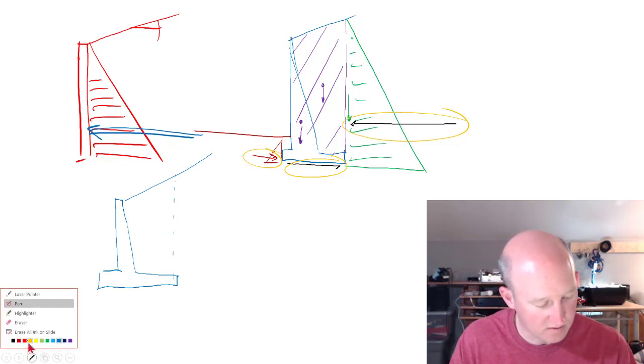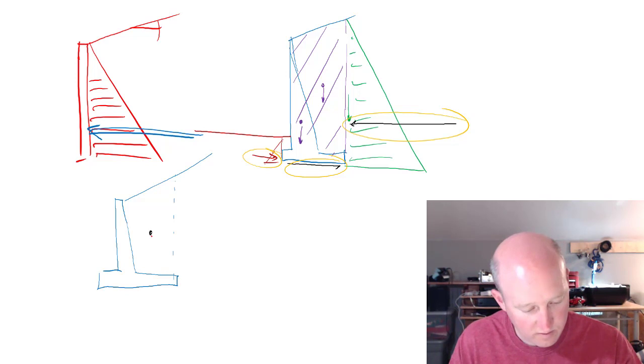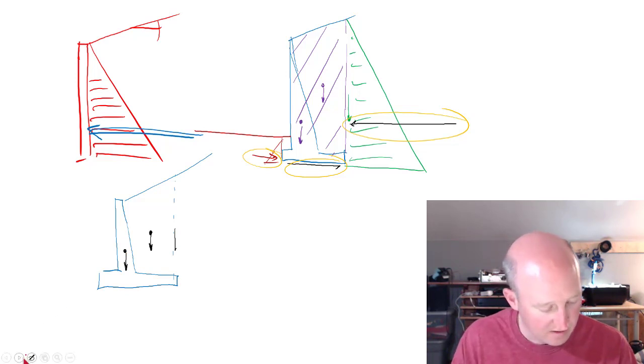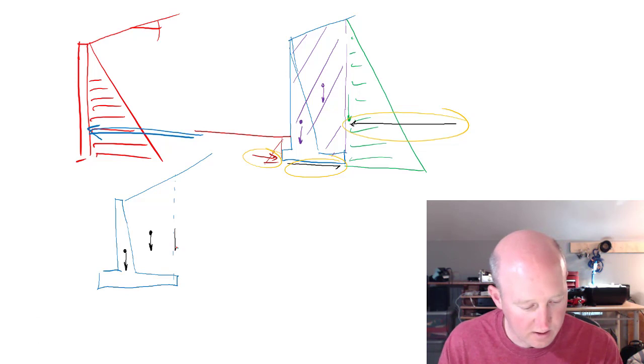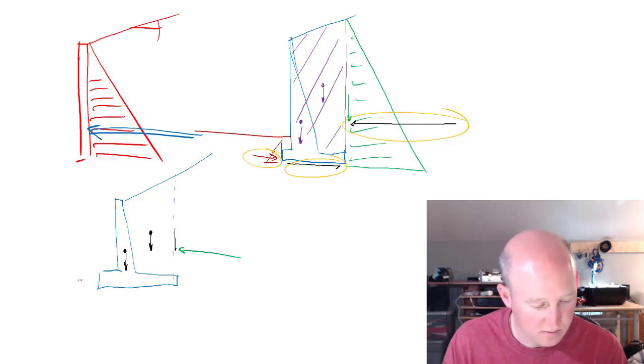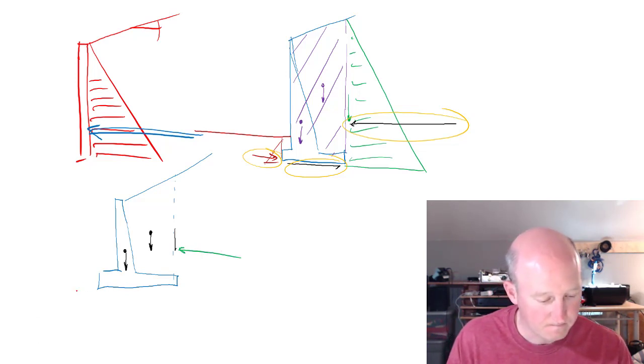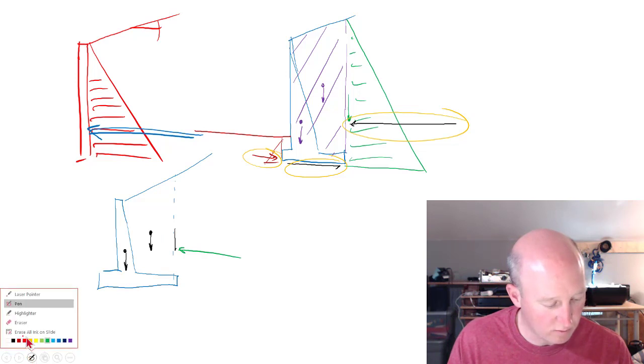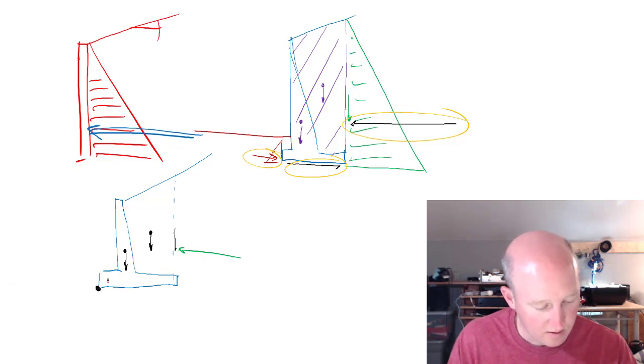with all of these same forces, so we've got a weight of soil, we've got a weight of concrete, we've got a frictional force that's acting on the back of the wall, and that's due to the soil failing. And then we've got a horizontal resultant. And what we would do is we would analyze this thing as a sum of moments about this toe.